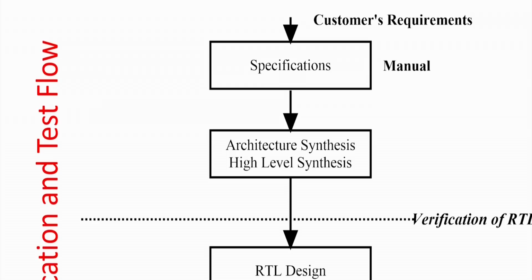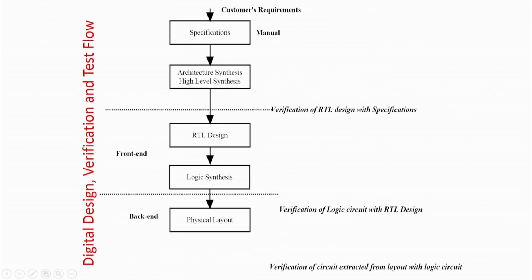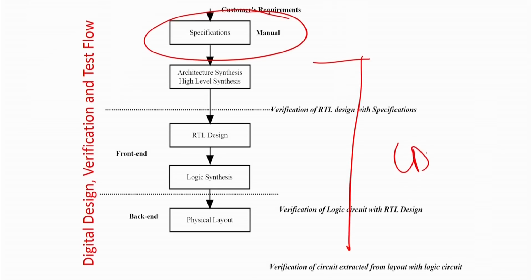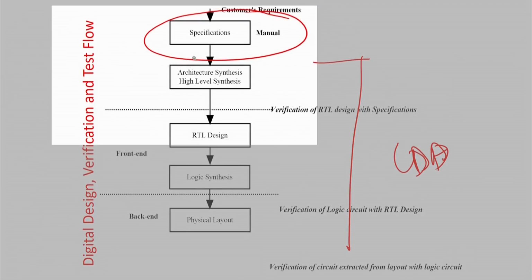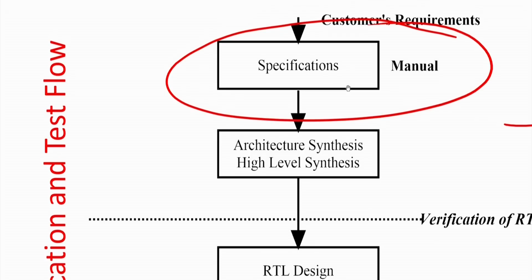After that everybody knows how an adder is to be implemented, and there are automatic tools which will do it for you. But whether you exactly require a serial adder, or a carry look ahead adder, or you want to implement a multiplier by using adders, nobody can do that automatically. That is the specification, and the high level design block diagram is a manual procedure. So you have to give good quality inputs to the tools, after which all of these are CAD tools. Given the specification, you have nicely designed the block level diagram and how it should be implemented. So this RTL is done, that is given to you.